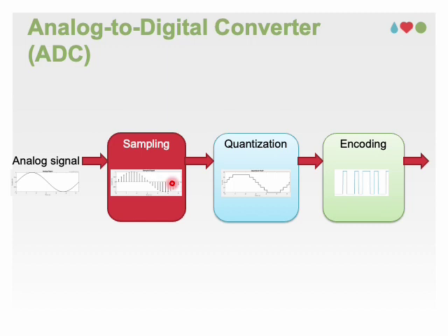It means that time becomes discrete while amplitude remains continuous. This sampled signal is quantized, at which point the amplitude becomes discretized. The last part is about converting the quantized output to a sequence of binary strings.